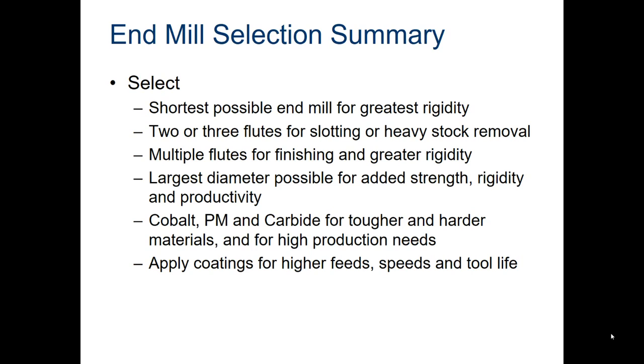One of the big problems with drill presses is there's usually too much vibration within the cutting head as you're doing that drill bit down in there. And so you don't get good dimensional tolerance. That's why with the mill, we want everything to be as rigid and solid as we can. The shorter the end mill, the less vibration you're going to get, the less dimensional tolerance problem, because it's not going to vibrate as much. And so you're going to get things a little more accurate.